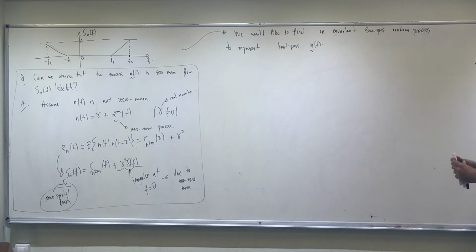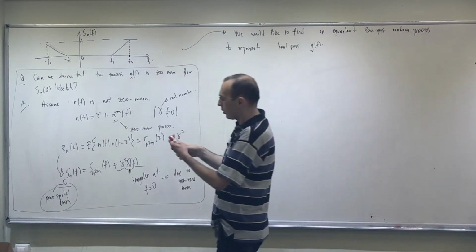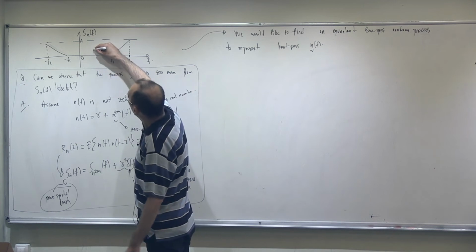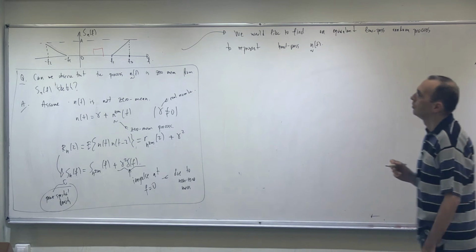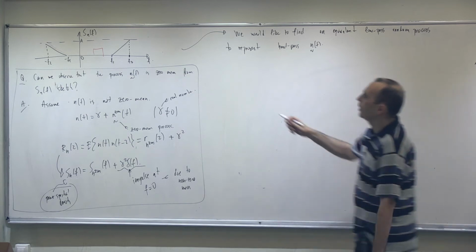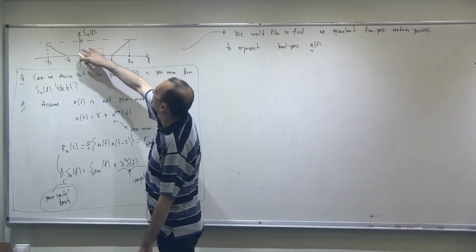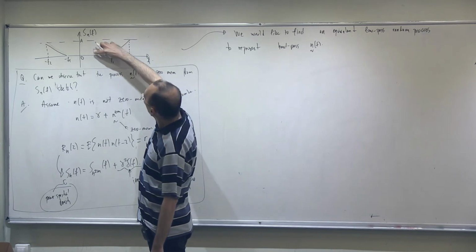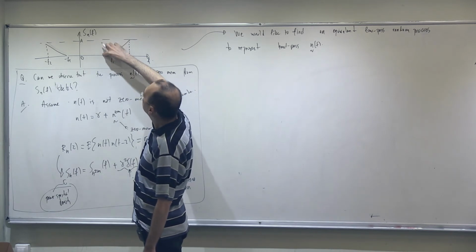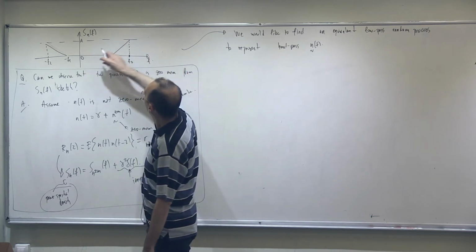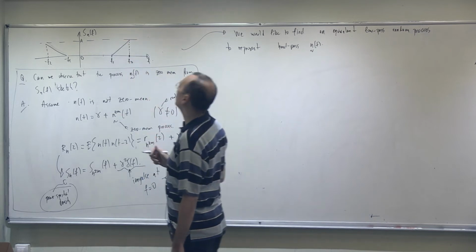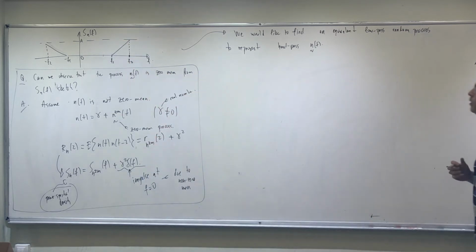Okay. So clearly, for example, if you construct a filter in this band, the output power of that filter will be equal to 0. It is an LTI filter only capturing the components of this random process in this band. The output power of this filter will be equal to 0 because there is nothing to capture, obviously. Only the frequencies in between f1 and f2 will make that filter produce a non-zero output. Okay, that is the case.